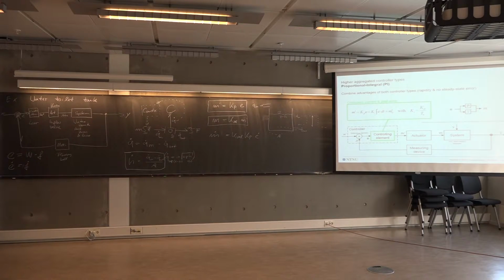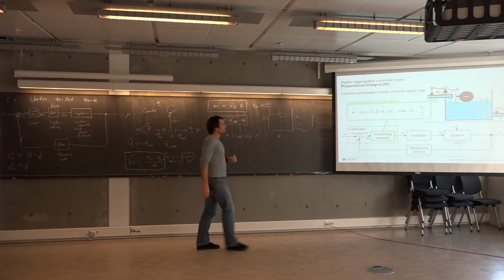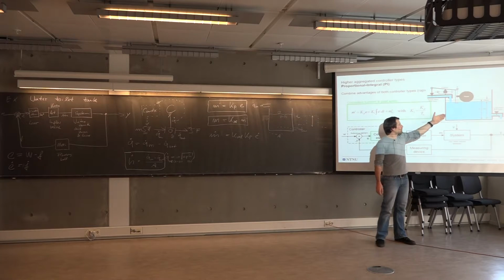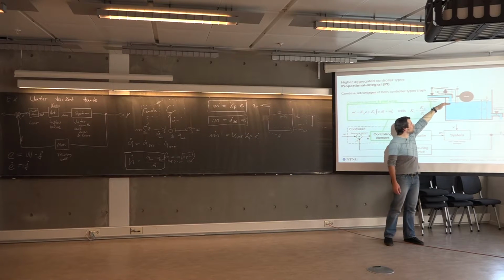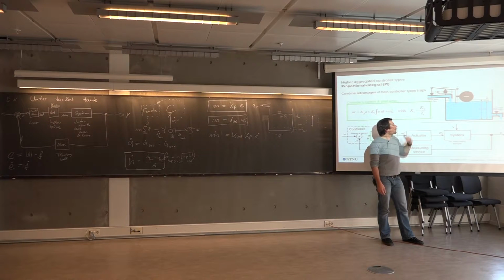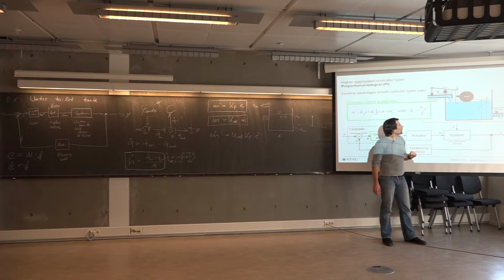And this is actually reasonable with regards to the water toilet tank, because in order to get rid of the steady state error, which in this case shows the steady state situation, we have a certain offset here. Inflow equals outflow, right? So the rate of change of the water level in the tank is basically 0. The water level is steady, but it's not the initial value. There is an offset.